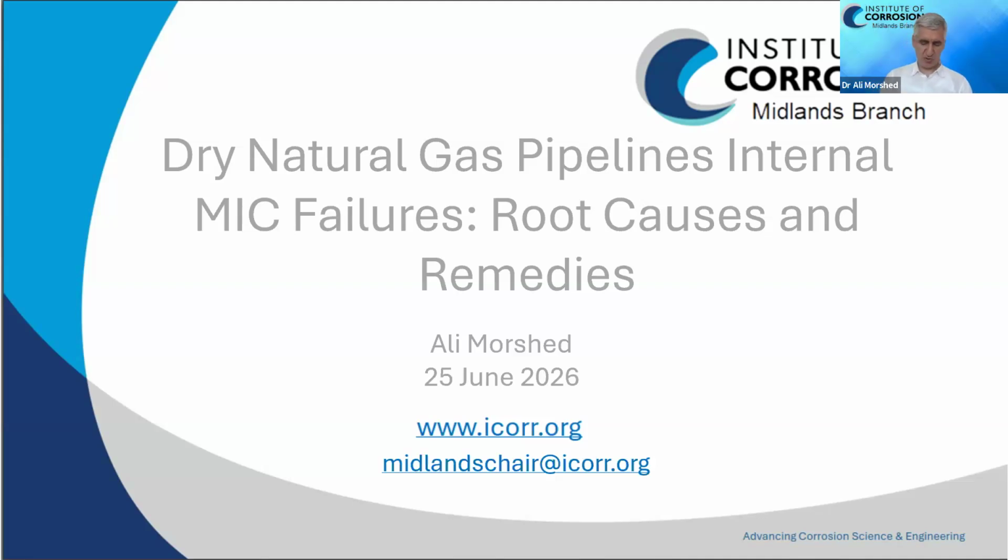So today I'm going to talk about several MIC failure cases associated with gas pipelines, and we were very surprised to see that in a system where we were not supposed to have any water, we were getting microbially induced corrosion inside the pipeline.